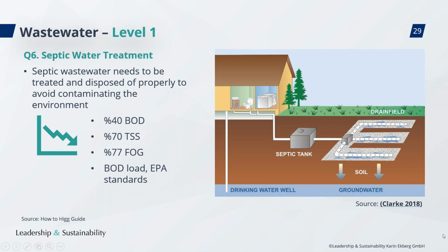And then here you can see also that you do need to have the treatment of the septic wastewater. And here are some general treatment efficiencies that you can reach. So you see it's not too high. BOD 40%. It's not really too high.